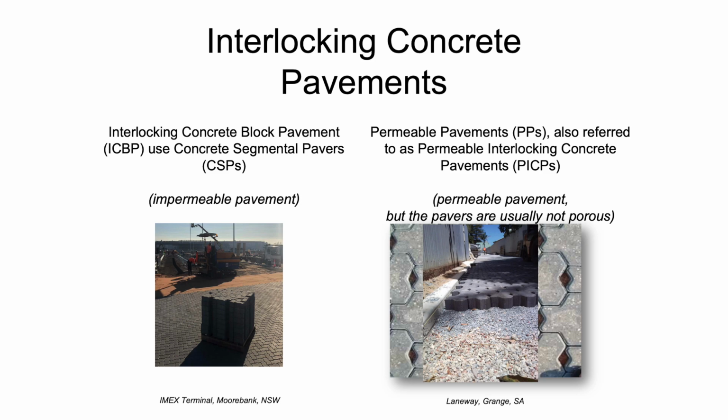So I just wanted to explain the difference between them because they are fundamentally different. And I think a lot of the early mistakes that were made in Australia, systems I've seen that are not performing today and perhaps are clogged today, are because people were sometimes designing both these and getting mixed up. So I have seen permeable pavers go down onto sand, for example. You should never see sand anywhere near a permeable pavement system. They should be bedded on, as Arlene said, 2 to 5 or 2 to 6 mil gravel. But you always put interlocking pavers that are impermeable on sand.